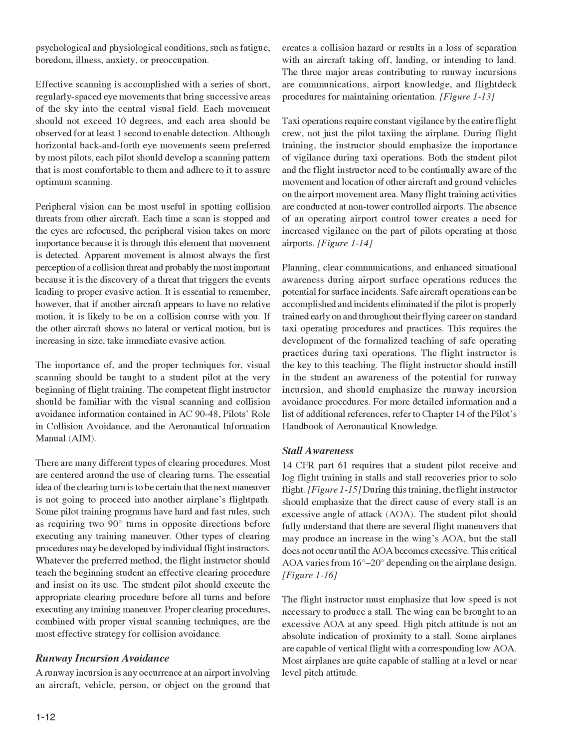Figure 116. The flight instructor must emphasize that low speed is not necessary to produce a stall. The wing can be brought to an excessive AOA at any speed. High pitch attitude is not an absolute indication of proximity to a stall. Some airplanes are capable of vertical flight with a corresponding low AOA. Most airplanes are quite capable of stalling at a level or near level pitch attitude.